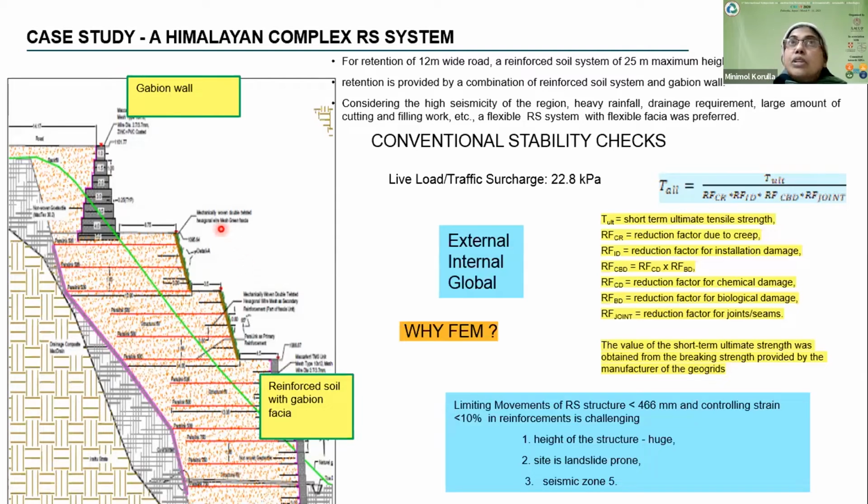And now coming to the reinforced soil structure, that itself is a composite soil reinforcement system, where the main reinforcement is a polymeric element. It is a polymeric element, two types of geogrids, where the bottom blocks have a strength of some 700 kilonewton per meter, and the top blocks have the main reinforcement of 500 kilonewton per meter as the short-term strength.